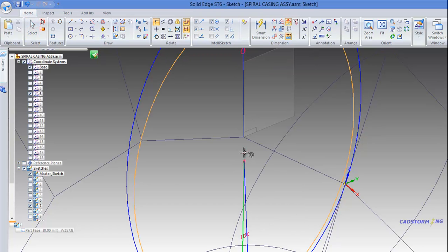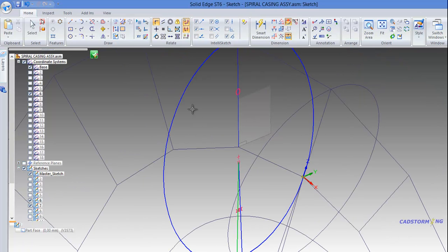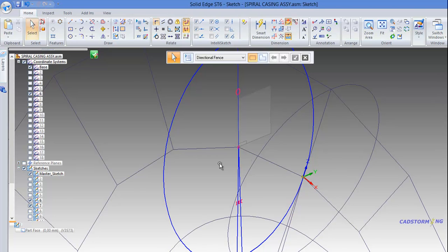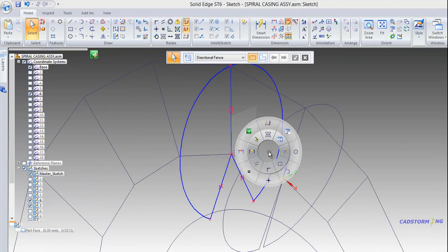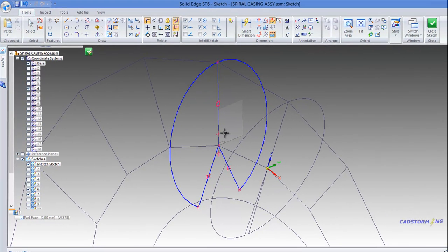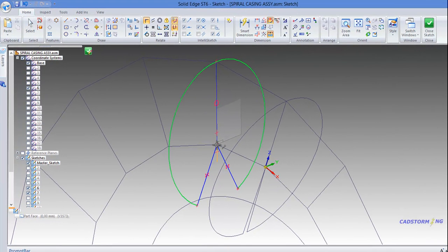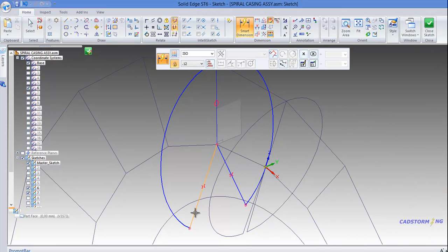So connect it to the center of this, to this point first, and then I have to look, it seems like the arc is already in the correct position. No, so the center of the arc is to connect, so select it and snap it there, and then I just have to add the angle, press A on the keyboard and change the value, and there you go.